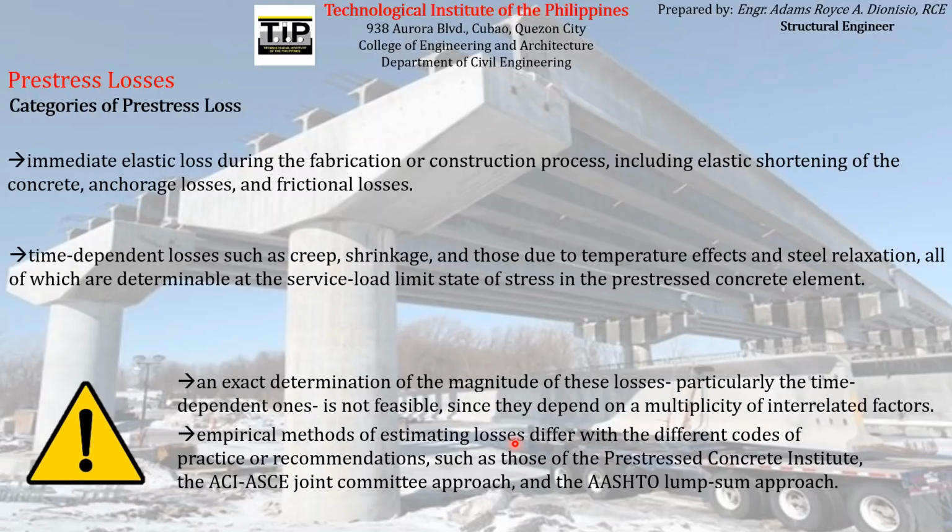We have different empirical methods for estimating these pre-stress losses, depending on which particular code of practice or recommendations you are using. You can use as reference the Prestressed Concrete Institute, the ACI-ASCE Joint Committee approach, and the AASHTO lump sum approach in estimating the pre-stress losses.